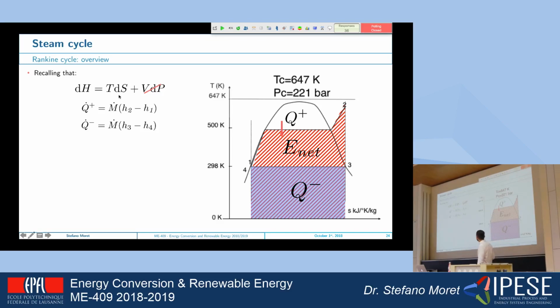So for the irreversible real cycle, the amount of work that we can produce out of the Rankine cycle corresponds to the red area here. That's why the TS diagram is so used: you just have to draw the cycle on the diagram, and the area already gives you an idea of how much work you'll be able to produce.